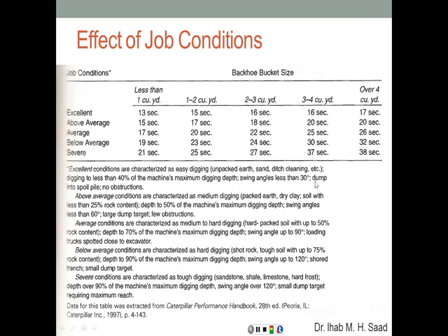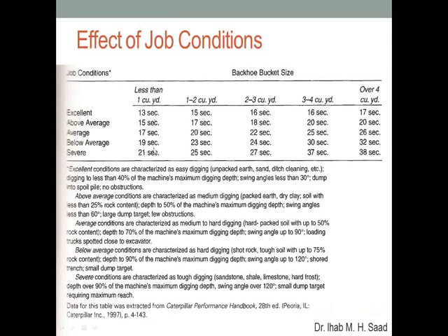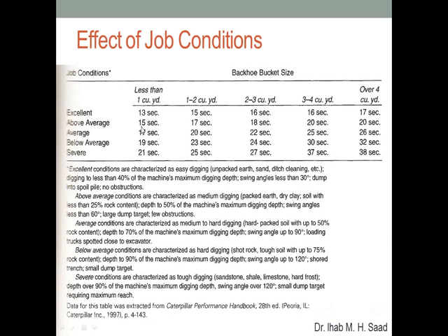So still, here in the first case we had 30 degrees, now we have about 60 degrees. It's still a large dump target, so it could be a large truck or an open area, and few obstructions. As you can see, that's going to extend the cycle time by about 2 seconds. 2 out of 13, that's almost 1/7, so almost a 14% reduction.